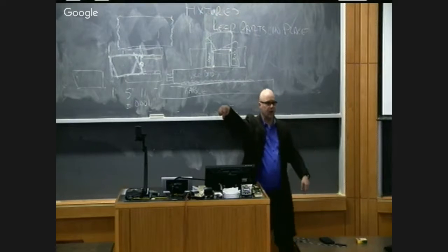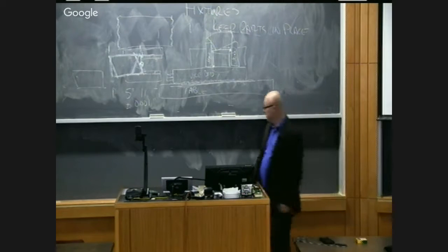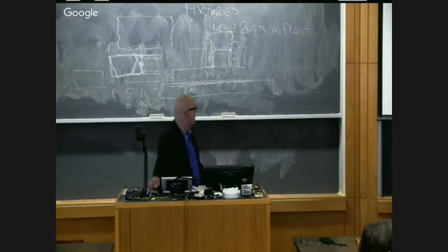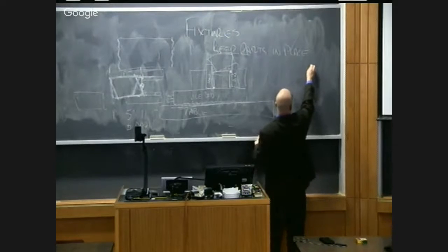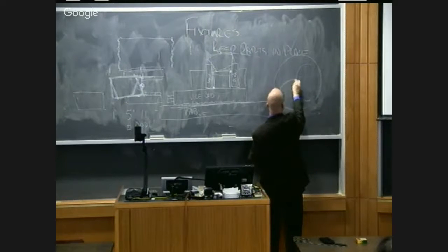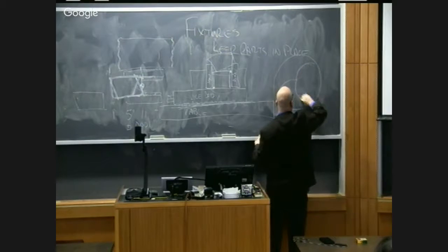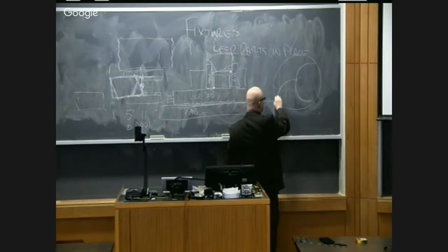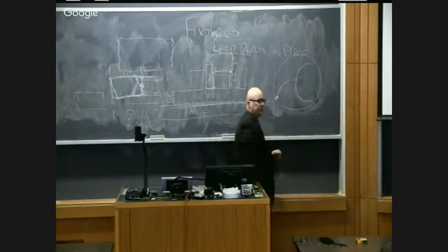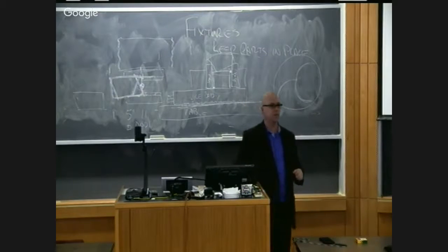So as you move in along the cutting edge, there's a flute at the bottom of most of those end mills. It's not like they don't have a cutting edge on the bottom. If we look at the bottom of one of those end mills, we're using 3 flute end mills. It looks like this. And so this is a sharp edge. There's a cutting edge there, a rake face on it, there, and there. And so the surface speed here is the spindle speed times the diameter of the end mill, convert the units, times pi, right?